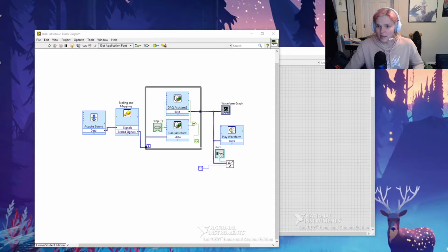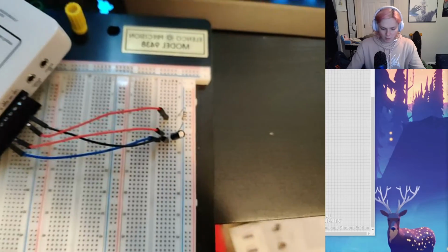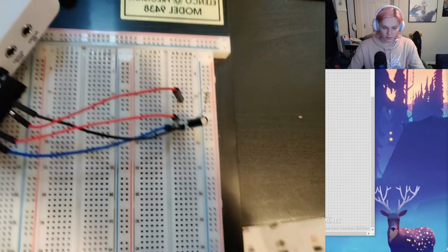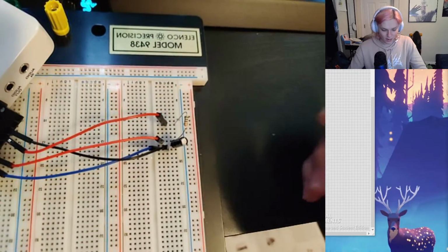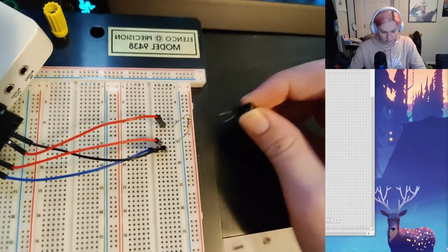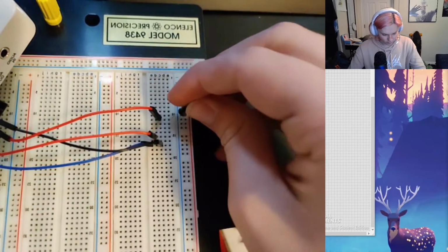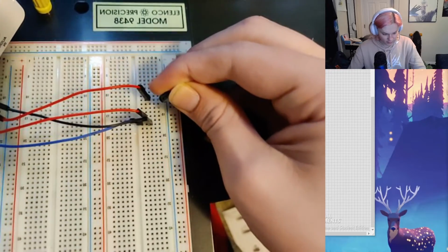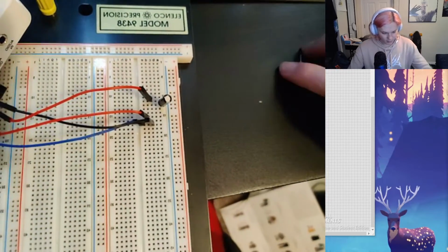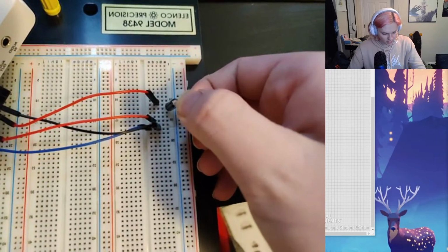As we saw in the lab, we can take our capacitor and turn it into a high pass filter as long as we just reorder things. So, in order to do this, let me refer back to this camera. Okay. All right, so basically we just have to flip our resistor and our capacitor. So take out the capacitor. Now we're putting the capacitor on the top and our resistor on the bottom.